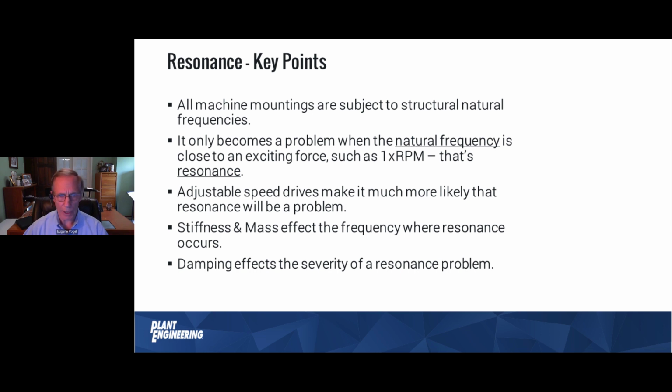All machines have natural frequencies. If you think about it, all machines have stiffness and mass and a certain amount of damping. So natural frequency is inherent to them. That natural frequency only becomes a problem when the frequency is close to some exciting force, for instance, perhaps 1 times rotating speed being one of the most common ones.